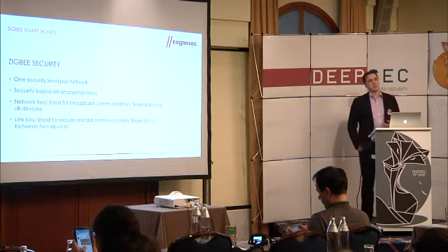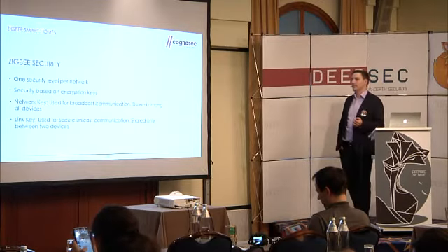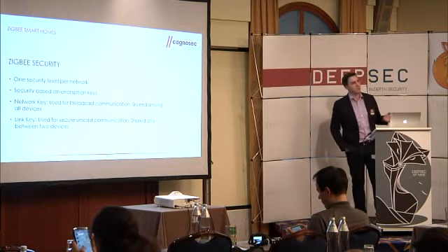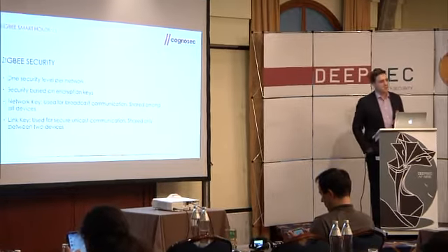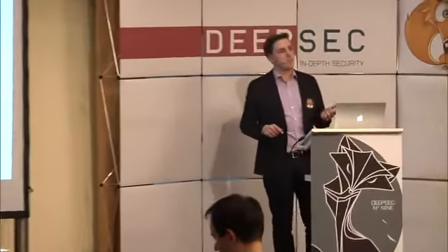So what else is interesting? ZigBee security. ZigBee provides 7 different security levels. This means you can apply a lot of combinations of what kind of MIC I want to provide, how long, what kind of key length. There are 7 different levels, but you can only apply one security level per network, which means that your lowest security capable device will determine the security level of your network.